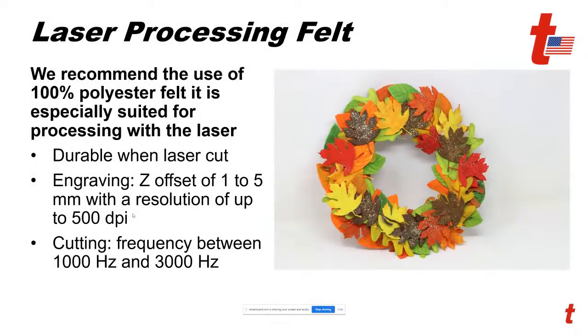It is probably most commonly cut with the laser, but can also be engraved. The synthetic ones are the more common. The ones we typically process are 100% polyester felt, well suited to the laser. I have found and tested just about every felt, and they all cut. Some don't engrave with a great contrast, but they all cut beautifully.